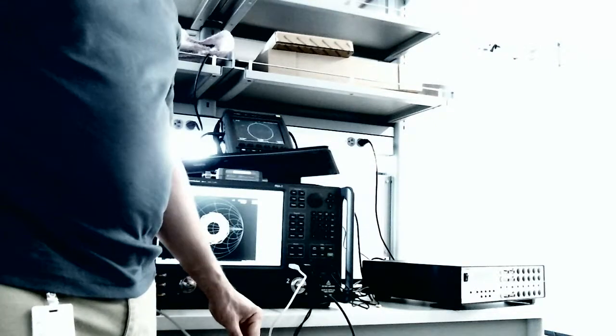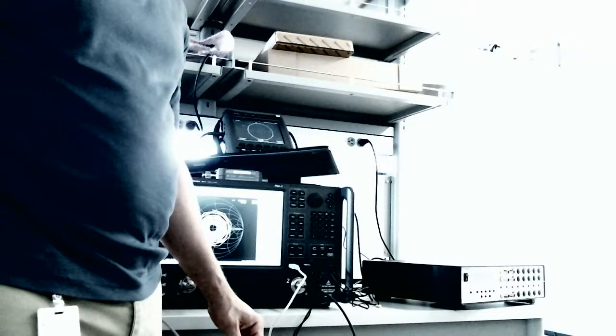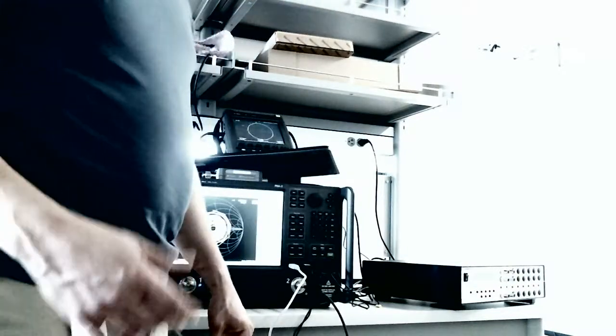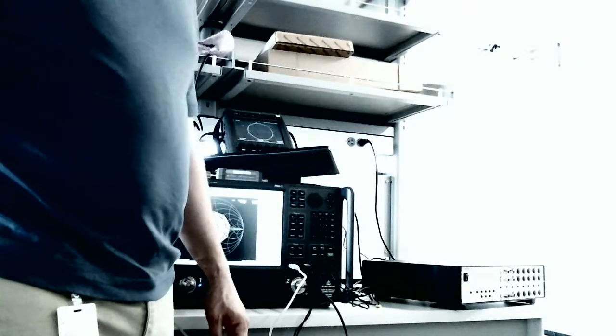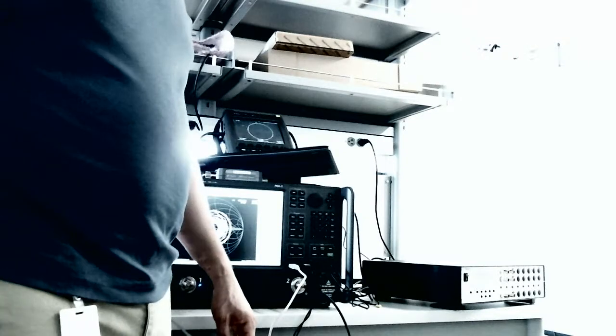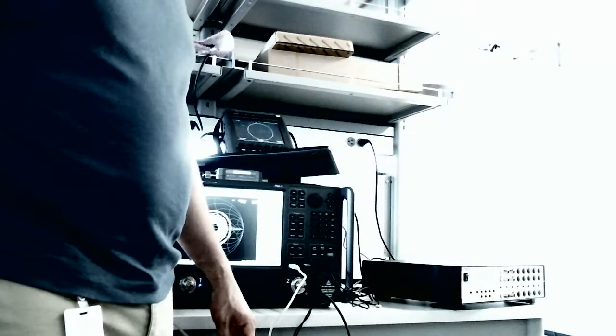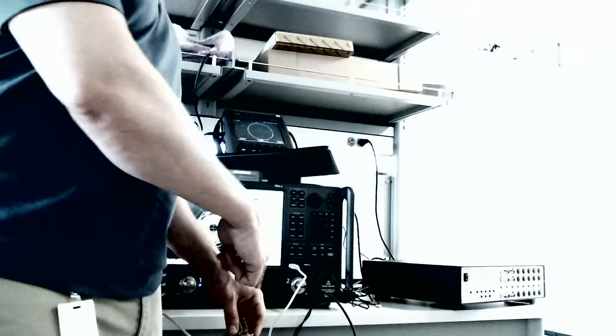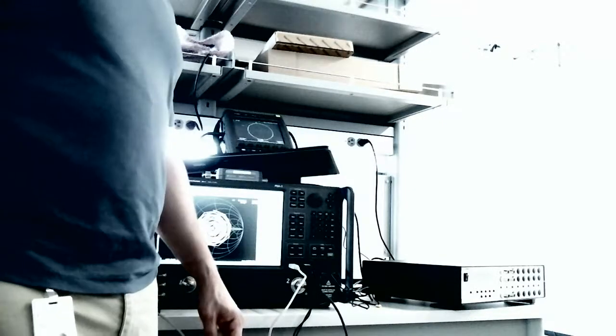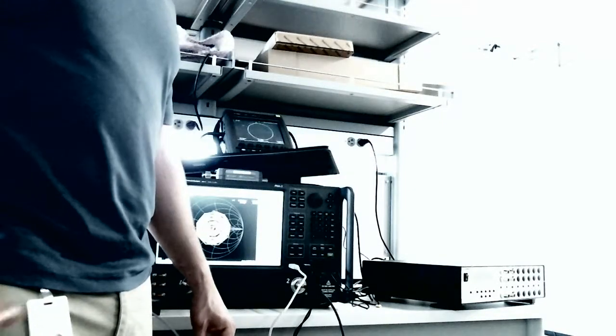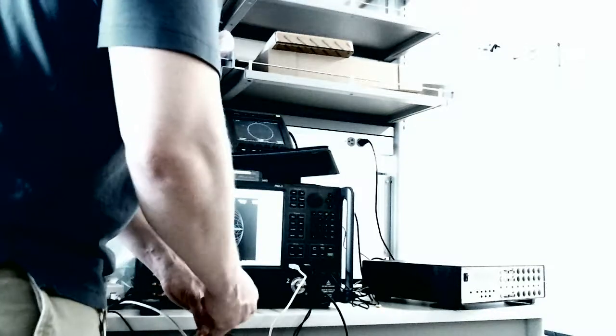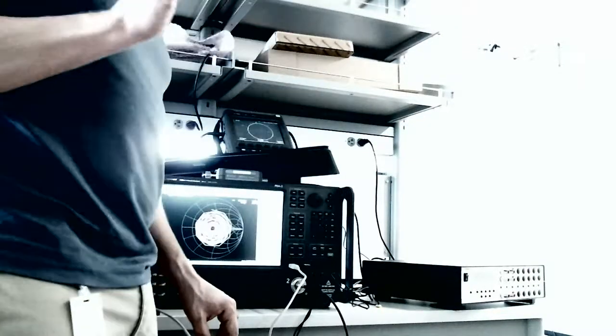I think it's not just the capacitor. Nanofarads most probably. It also depends on frequency, right? The capacitance, yes. The issue with these kinds of mounts is that at high frequency they're not very good. You might be able to do it at a couple hundred megahertz, but surface mount is the best way to go.